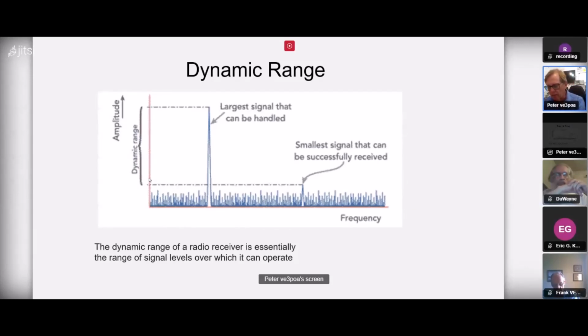The high-level mixer operation is one of the key components to ensure a good dynamic range and overload performance. The design of the radio should ensure that the mixer is not overloaded, and the use of a high-level mixer, like one designed to accept the high-level LO. In this way, it can tolerate high input signals without degradation in performance.